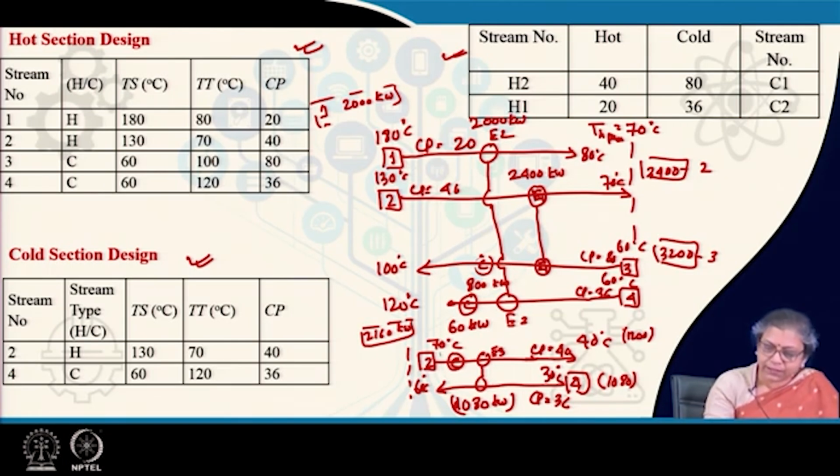This one, sorry, in this particular case is a hot end, so I am sorry, there has to be heaters, very sorry. So therefore, there are heaters here, and here I have put a cooler in this particular case. So this particular cooler is going to cool this stream, it requires 120 kilowatts. Actually, what I should have done is I should have placed the cooler on this side.